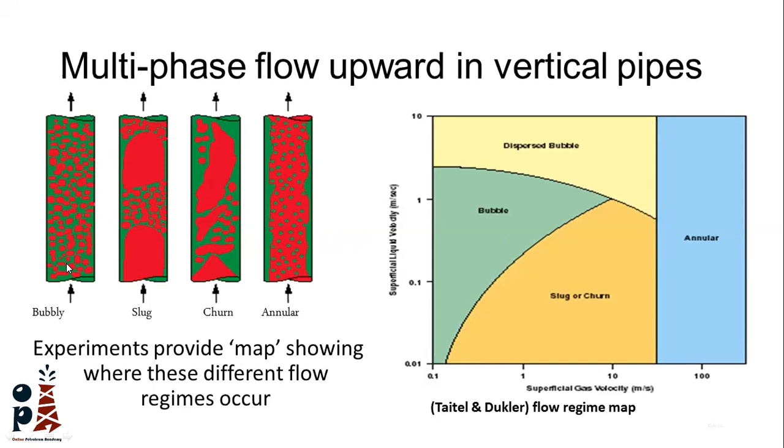So the continuous phase will most likely be the liquid, while the bubbles of gas will move through the fluid. As you go up, expansion happens and the gas expands more, and you will see a slug shape. Then it begins to connect more into a churn shape, and it ends with the annular flow or the mist flow, where the continuous fluid becomes the gas.